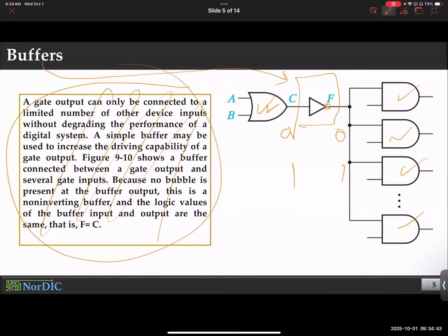Basically, one thing that you must have seen, that when you insert a logic gate, think of them like a chunk of capacitors. Any logic gate, if there is nothing else, will bring in capacitors. So by inserting buffers, which doesn't change anything, you are adding delay. So that's good. Buffer insertion is a step in VLSI design, very large scale integration design, that people often use to balance out the branches.